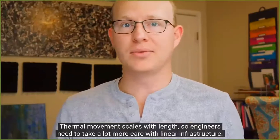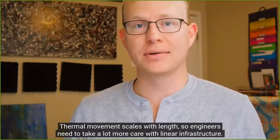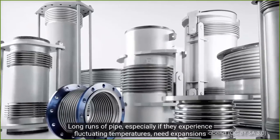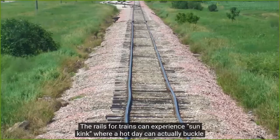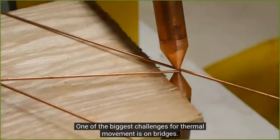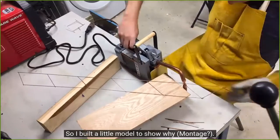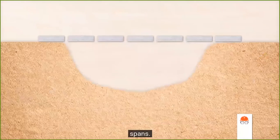Thermal movement scales with length, so engineers need to take more care with linear infrastructure. Long runs of pipe, especially if they experience fluctuating temperatures, need expansion joints to prevent damage. The rails for trains can experience sun kink, where a hot day can actually buckle the steel. One of the biggest challenges for thermal movements is on bridges, so I built a little model bridge to show why. Unlike sidewalks that can have periodic expansion joints, bridges only have support between the spans.